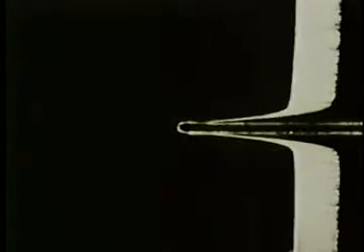The thickness of the boundary layer increases along the length of the plate. Fluid deceleration is transferred from one fluid layer to another by viscosity. Moving the camera with the free stream velocity will give a better view of the boundary layer growth. The velocity throughout the boundary layer is less than that in the free stream. There is no slip between the plate and the layer of fluid immediately adjacent to it. At the plate, the relative velocity is zero. This is the no-slip boundary condition of viscous flow.